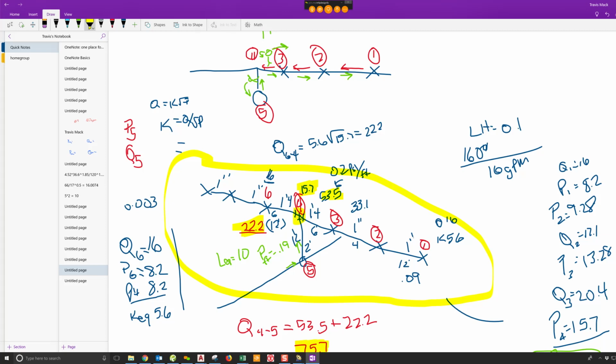If they weren't getting the same answers, then they had to redo it. Because if you're doing a simple tree system, you should be able to get exactly what the computer gets within some rounding errors. Because I know AutoSprink carries things out to 7 decimals. So where we were going out to 1 decimal here, AutoSprink goes out to 7. You're going to have some differences with that, because I wouldn't want you to carry things out that far. But that's generally what you're looking at. And again, if you can plug and chug and get these, you'll be able to get through your nice set 3.